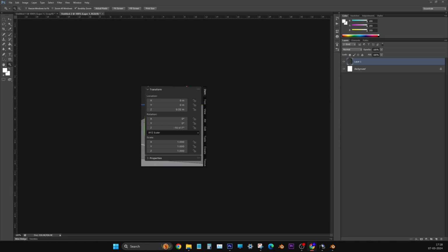So all the other objects on top are all instances. Only the one at the very bottom, the first one down, that cube is the original. So when you change the bottom one's shape, see, all are changed, right? That is why we work on just one staircase step, and all the other staircase steps change shape.